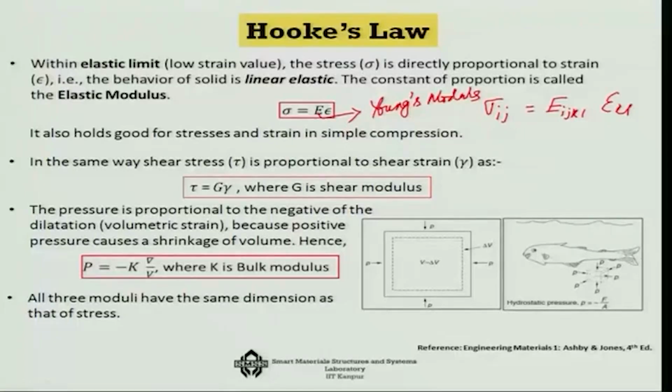Now, the way a normal stress component is proportional to a strain component and related by Young's modulus, similarly, if you have a shear stress component, that will be proportional to shear strain, and there the modulus of elasticity is referred to as shear modulus, or G.